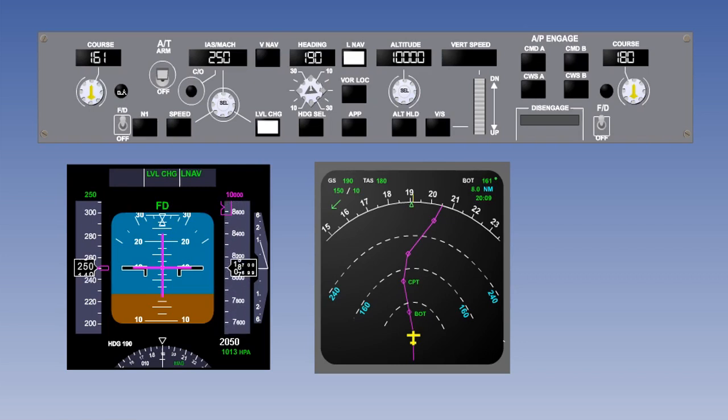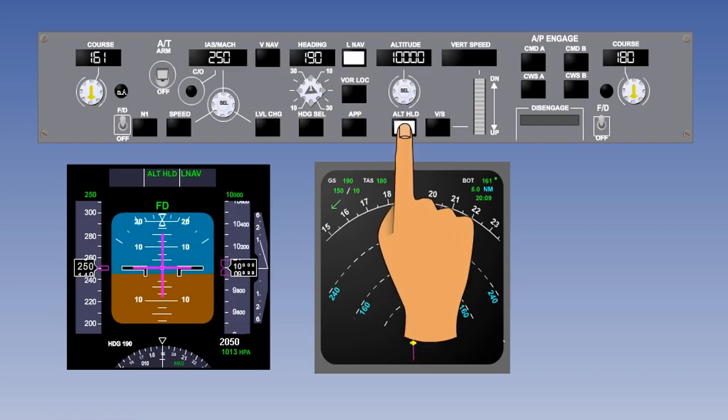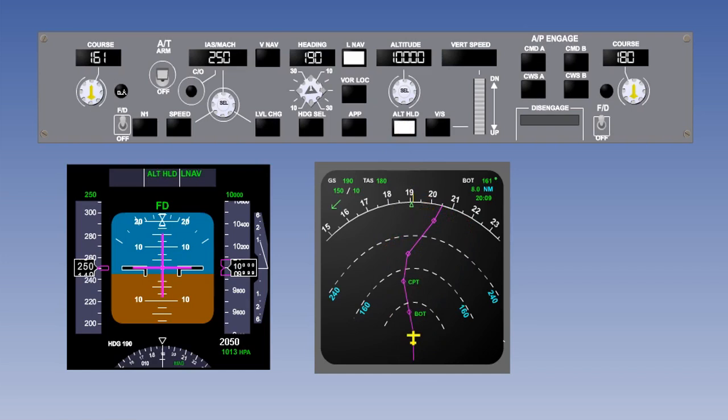As the aeroplane approaches the desired height, the flight director commands a level off attitude, and if the pilot did nothing else but level off, the aeroplane would then accelerate, so he also has to decrease the power available. He would also select altitude hold again to accurately maintain the desired altitude.